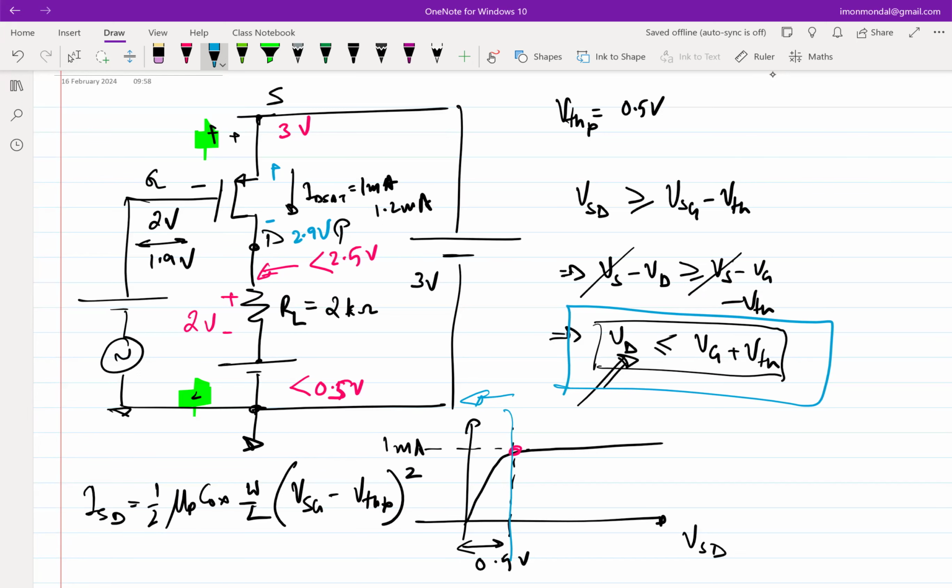So what is the solution? The solution is to ensure that the transistor is biased away from saturation, somewhere on this side. How far we have to go on the right side depends on how much margin you want, or in other words, how much swing you are expecting at the output. Let me even take a step back. Why should I bother about swing?